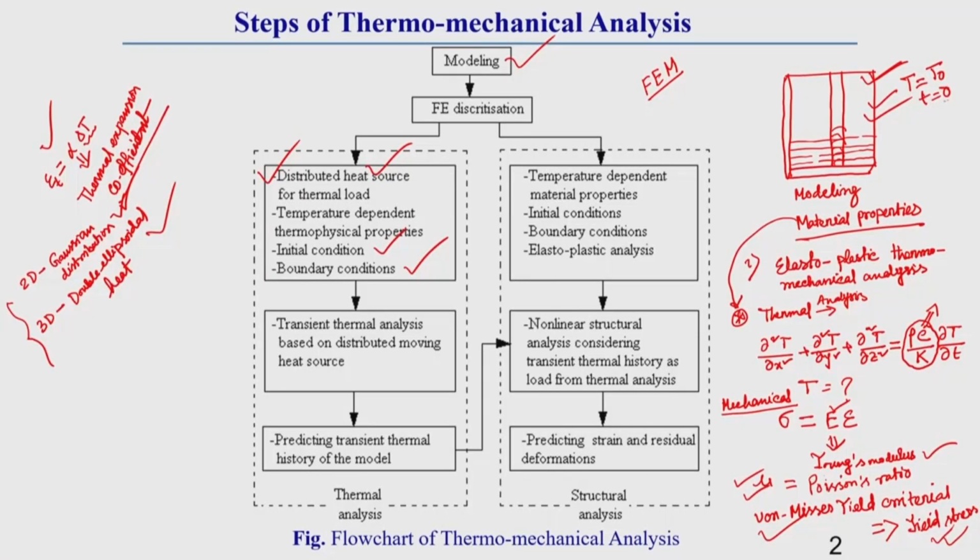Okay. When time t equal to 0, this is called the initial boundary condition, that means the whole plate temperature is T0. Now, two other boundary conditions which are popularly used in welding: one is called Newtonian convection cooling boundary condition, another one is called radiation boundary condition.